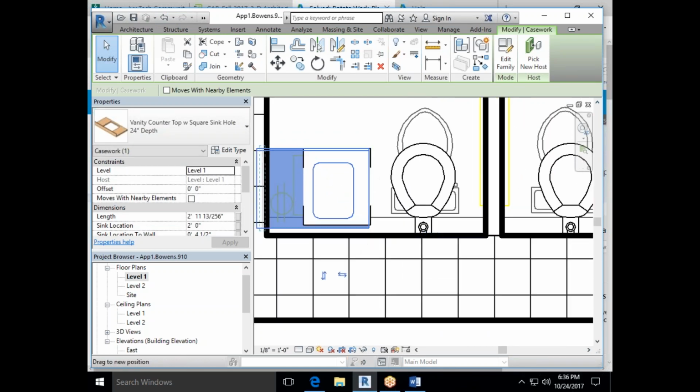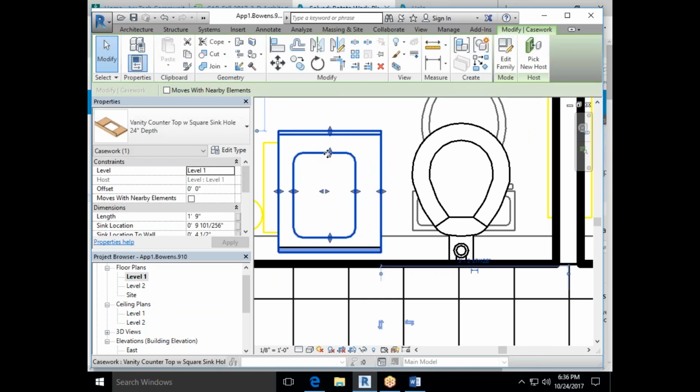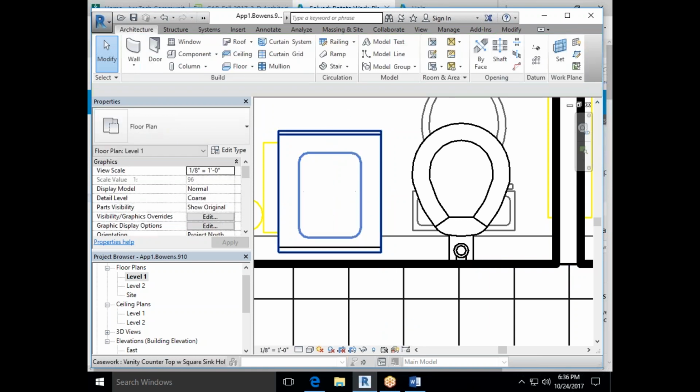They all just stretch and snap until it fits, okay? It seems a little finicky, but you eventually want your edges snapped on all edges. And then this guy, I think you can also move him to be centered if you drag the middle arrows, and then it'll center itself about the existing countertop.